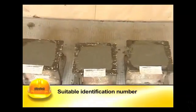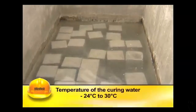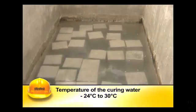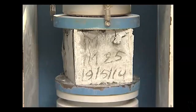The cubes should be marked with suitable identification number when slightly hardened to facilitate easy identification at different ages. After 24 hours, the mold is stripped off and the cubes are to be stored in water for further curing till it is taken out just prior to testing. Curing water temperature should be maintained at 24 degrees Celsius to 30 degrees Celsius. The cured cubes are then tested on a compression testing machine after 3, 7 or 28 days.